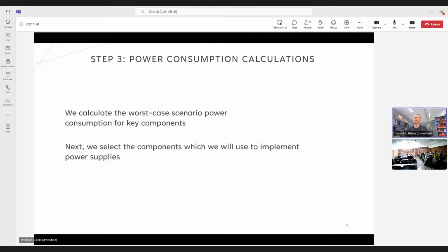Yeah. So I'm asking the following, and I will tell you how. You saw this number of rails. You are now acquainted that you need to provide the sequences of these rails. You will start some power supply rails before, some later. Some will be tightly related to the previous one. To understand that properly, you need to make a so-called power tree. It is called a power tree.